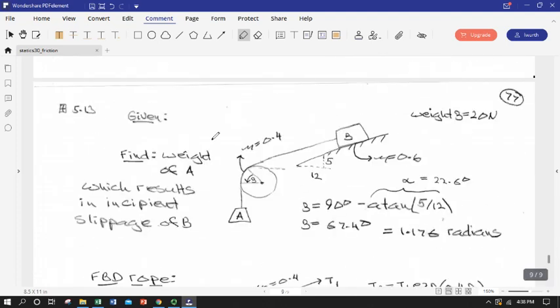Okay, let's fix things a little bit. Here's our first use of it. We've got a weight sitting on a ramp, and it's got some friction, and we've got a mandrel with a cable running over it, contacting it over an angle beta, which we're going to have to solve for with some geometry. And we've got a different friction, rope on mandrel, than block on slope.